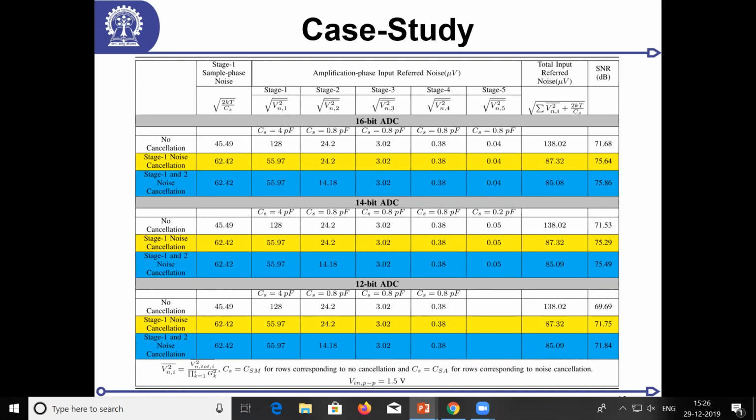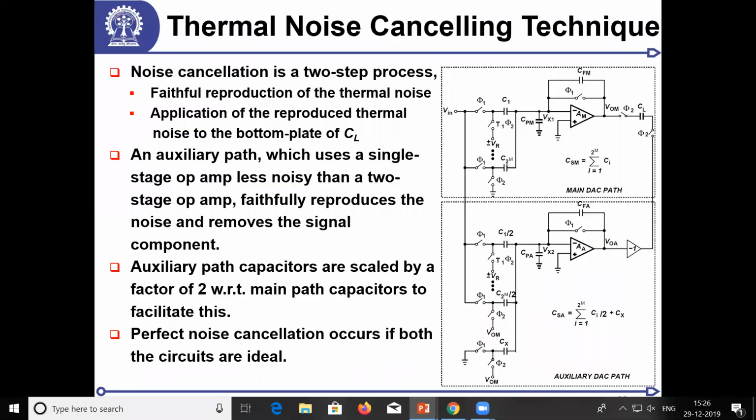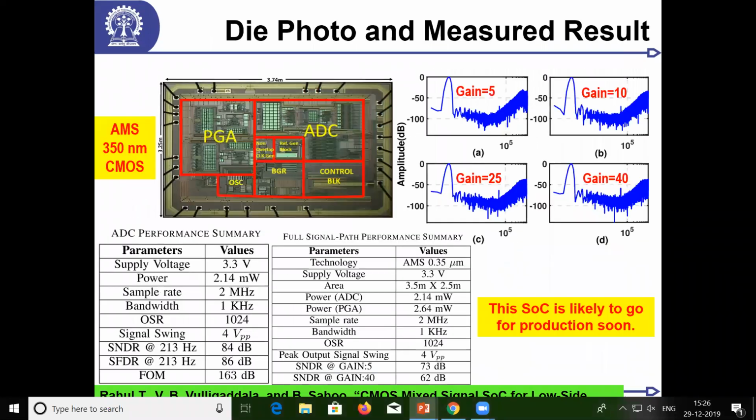A good analog designer will see a symmetry in everything. We human beings are almost symmetric around the center part. Almost all analog chips, like this one from ST Micro, show the amount of symmetry that goes into making an analog circuit. You can see that they are nicely halved. There is a mirror; every layout will be exactly mirror images. They look very symmetric, power delivery and everything.